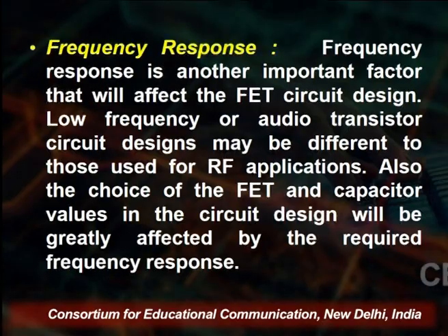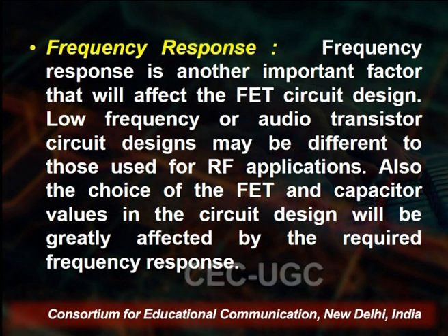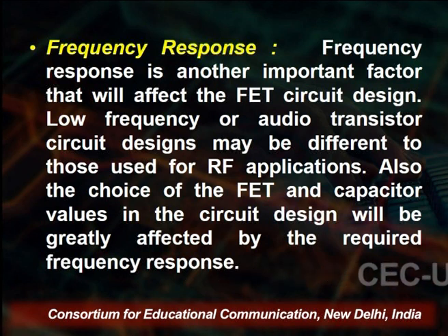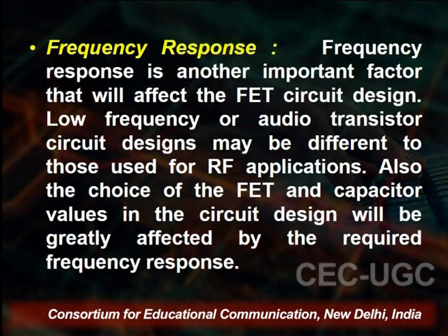The next important parameter is the frequency response. Checking the frequency response is another important factor for the FET circuit design. If we use low frequency or audio transistor circuit design, it may be different to those of RF applications. The choice of FET and the capacitor value in the circuit design will greatly affect the required frequency response. So, frequency response is one of the key parameters in the FET. What type of frequency we use, low or high, depends upon the required frequency response.